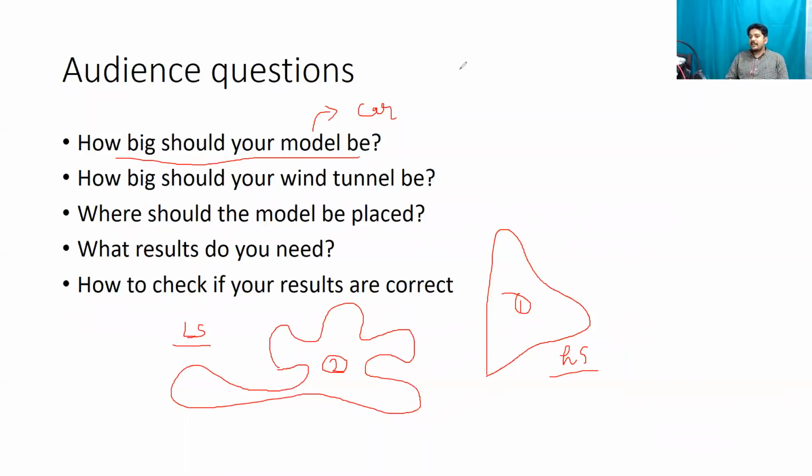Right, so this is one of the classical things that I hear from aerodynamic students or people who are interested in aerodynamics: hey, my computer is really, really small in terms of capacity. Can't I just scale down the model, right? It seems like a great idea, because you would think that when you scale down the model, you are still using the same mesh. And hence, when you scale down, the mesh that you use could be more than adequate for a smaller model, right? That's the thought process, which seems intuitive, but the mistake is the mesh is no longer valid.